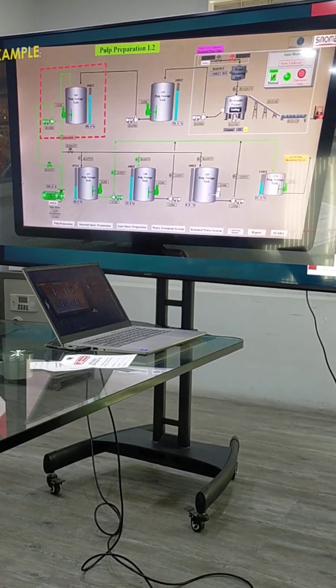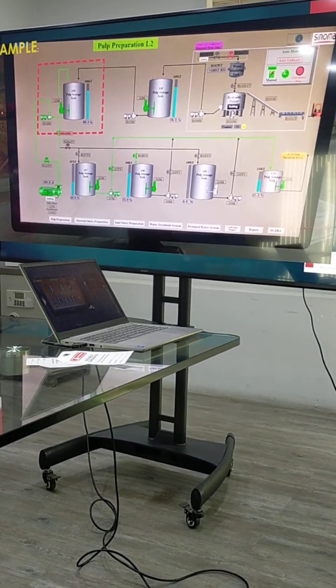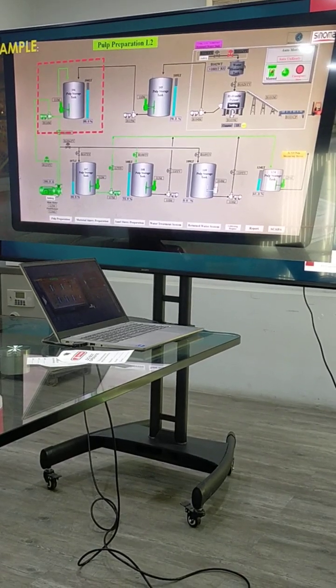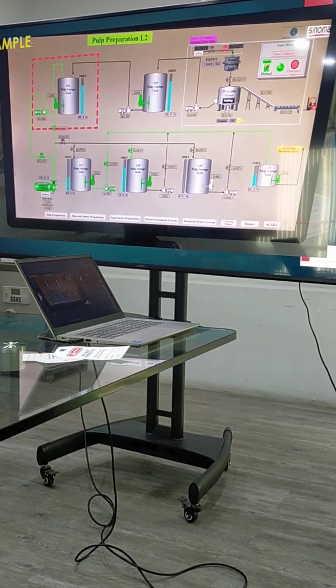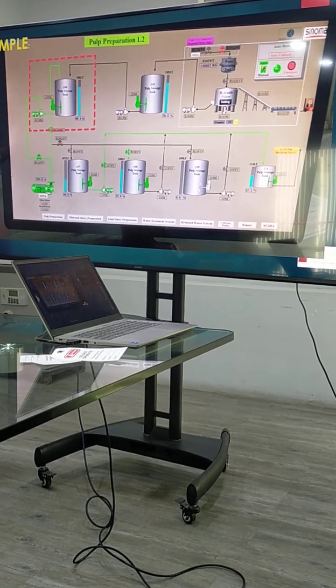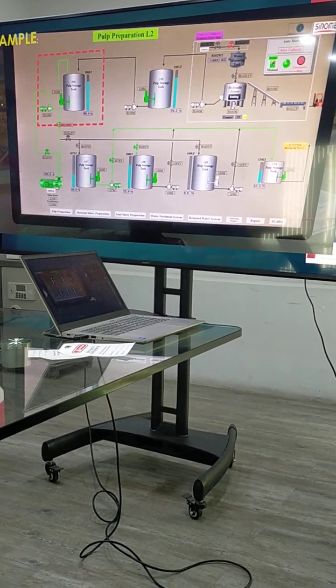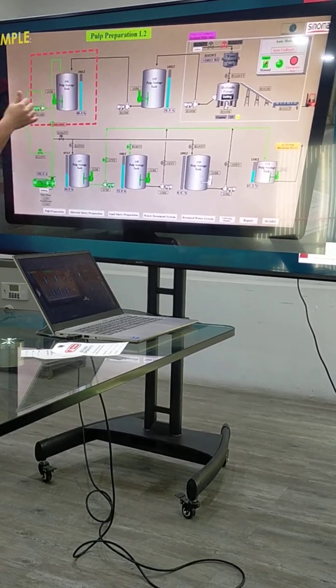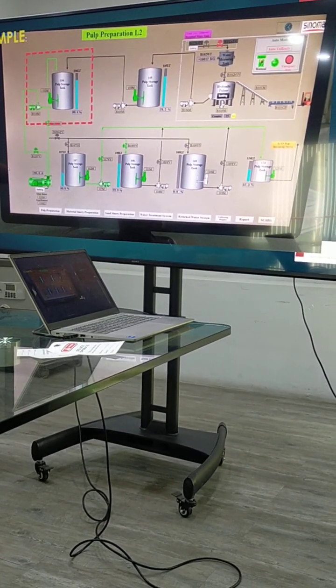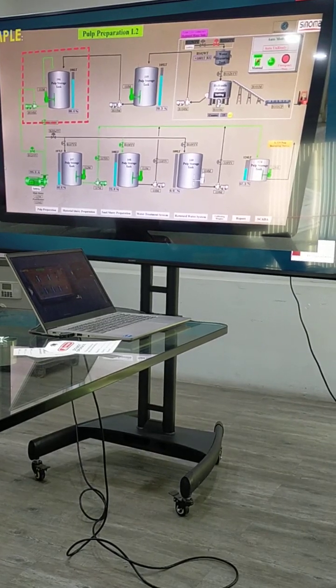The supply valve. Which valve? For example, the water supply valve. Yeah. What else? Compressed air. We have a lot of hazardous energy. Because you should always forecast, if you are inside the tank, what could come inside while you are working? What could harm you inside?